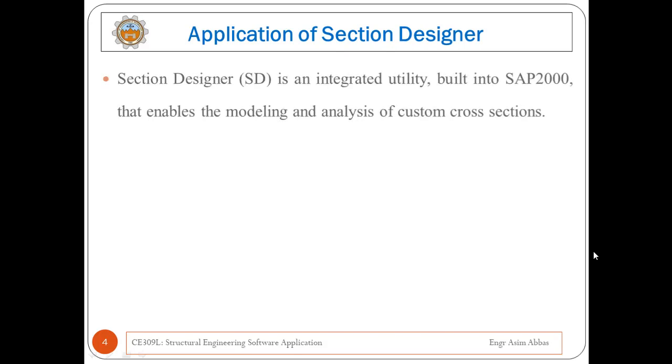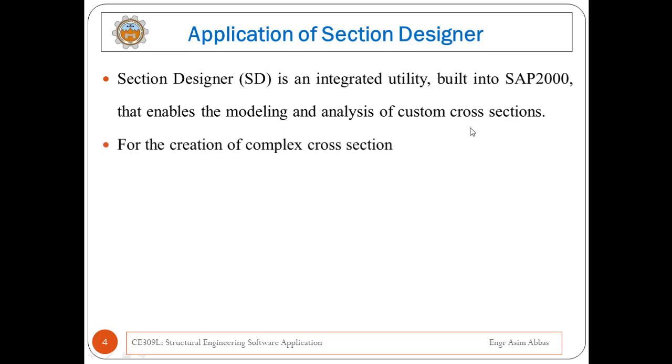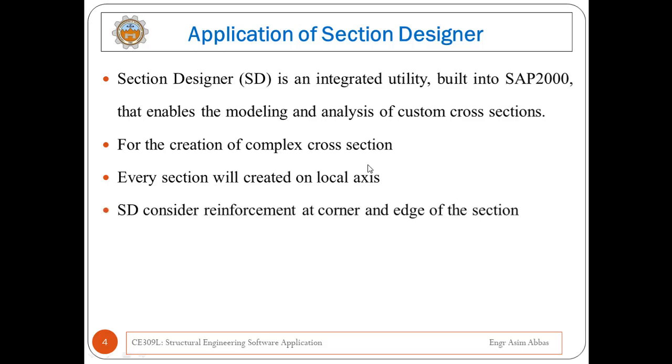Okay, application of section designer. Section designer is an integrated utility built into SAP 2000 that enables the modeling and analysis of custom cross sections. By using the SD, you can create any complex cross section that is not available in SAP 2000, and the cross section will be created in the local axis, right?